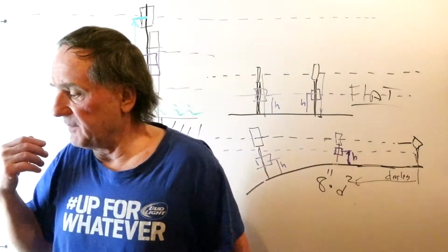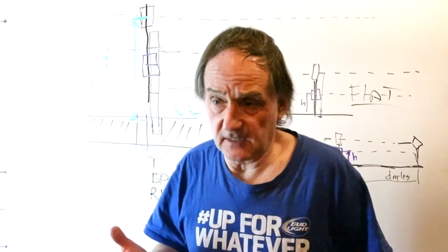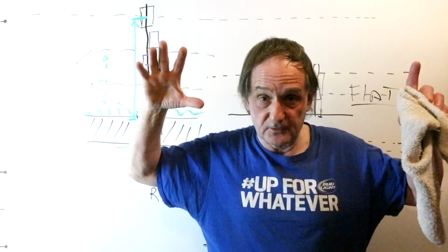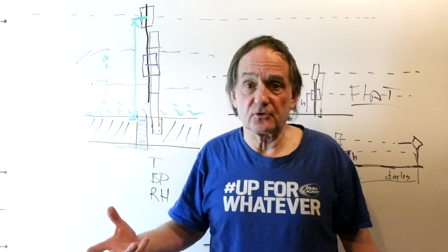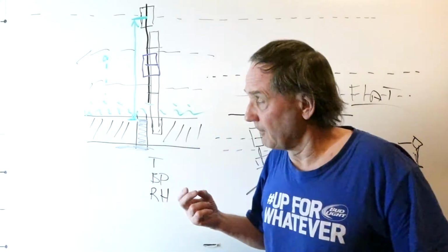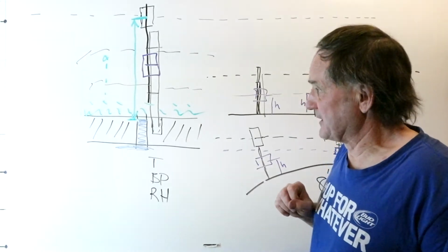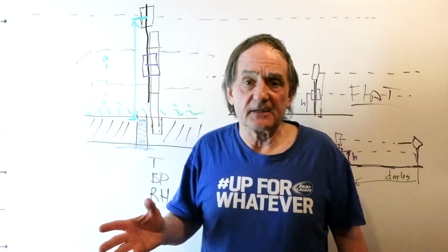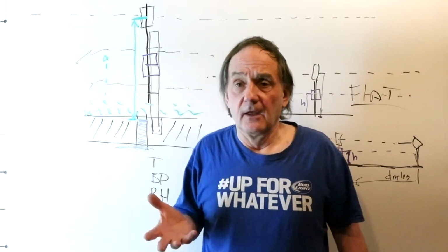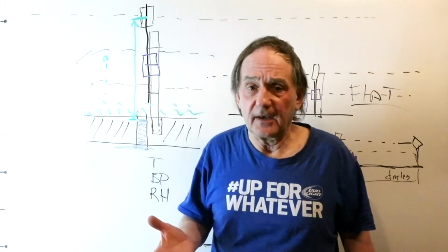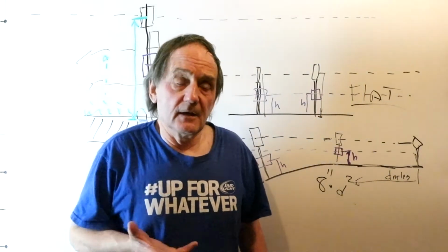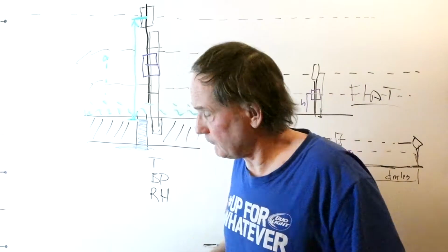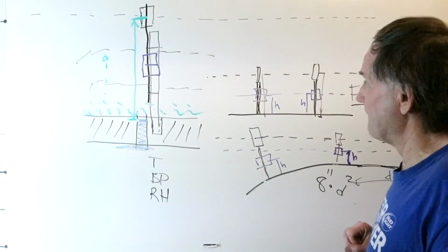And we also don't want to be making measurements near sunset or later in the day, because once the sun starts getting low on the horizon, the temperature starts dropping, and you get a lot of temperature gradients and a lot of refraction. The best times to be doing this is about midday or first thing in the morning, right as the sun's rising. The air really doesn't start elevating in temperature until about an hour after sunrise. It's a lot slower warming up in the morning than it is cooling down near sunset. So that's another thing to keep in mind.